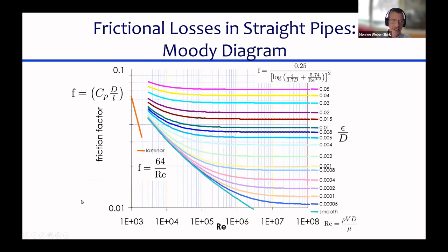Here's a Moody diagram, and we're showing this because this is how engineers used to, and I want to really emphasize, used to solve pipe flow problems. I think you should know what this looks like to have a sense of how this friction factor equation, the Swamee-Jain equation, what that shows, and how head loss increases, or the friction factor increases, as roughness of the pipe or channel increases. But this Moody diagram is a pain to use to actually solve a fluids problem.